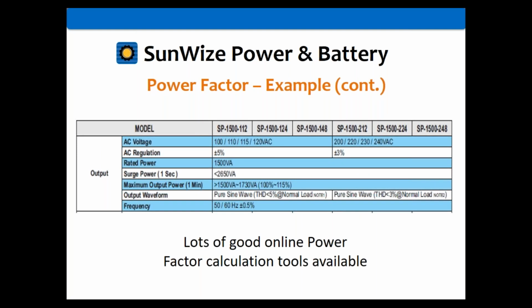So, like I said, sometimes you can see how this stuff applies. Thank you for bearing with me through all this stuff, but you can see why it matters and what it means. You may have been looking at inverter data sheets for years, not really understanding why it said volt amps and not watts. This is why it says volt amps and not watts. So it's important to keep that in mind. Again, if you've got a good load that has a power factor close to 1, it's not going to be an issue, because when you're at 1, your volt amps equals your watts. They're exactly the same thing. But anytime you're off of that 1 mark, it's not the same thing.